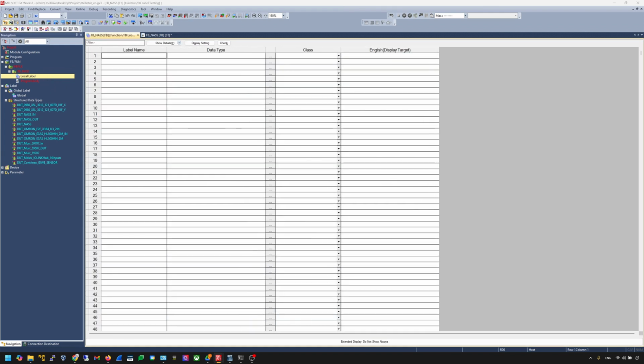And the first one, what is the interface you have? I have the in enable. Then I will have in data. One is data that comes from the IO-Link master or another field bus, and then out data is the data I would like to output to the field bus.